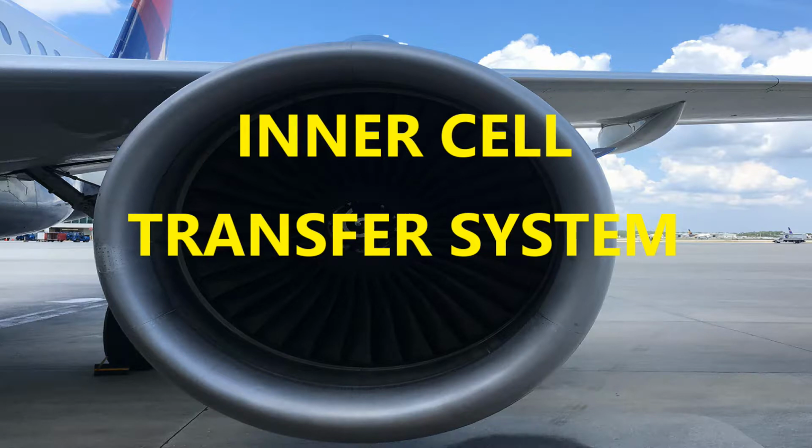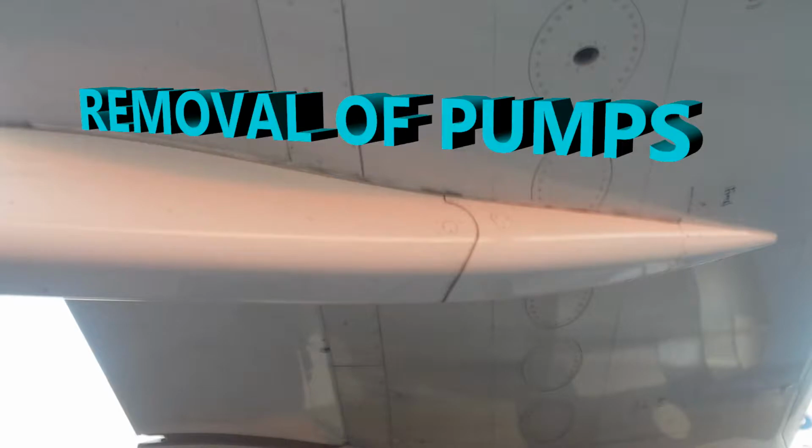Okay, if you're going to be removing any pumps, let's just say for the wing pumps to start. The wing pumps are located between ribs 1 and 2 under a cover plate and a fairing assembly, so you're going to have to remove those in order to get access to the pumps, right? And then the center pumps, they don't have a cover plate, but you can get to them through the hydraulic bay panels. So 2 different locations or access panels for accessing the center pumps versus accessing the wing pumps.